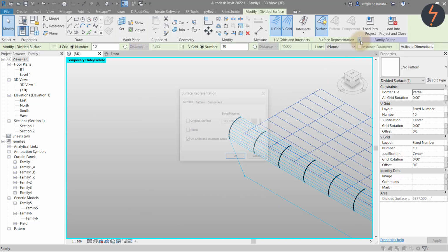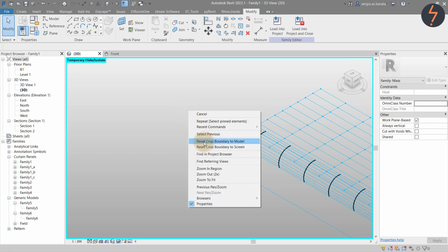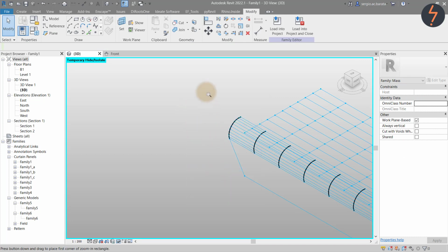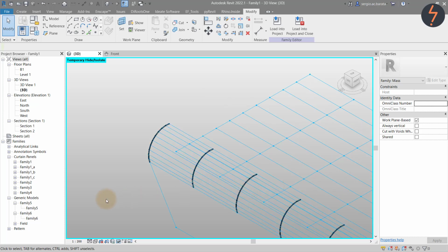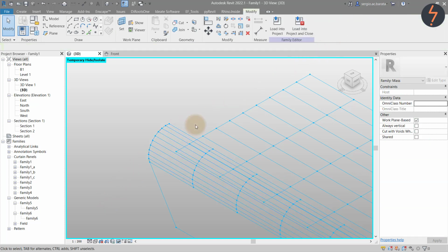I noticed that the flat roof section is missing the nodes, so I activate those. Zoom in a little closer to ensure I can see all target points clearly. Then from the project browser, find the modified Truss adaptive family called Family 6 and start placing this according to the point order.